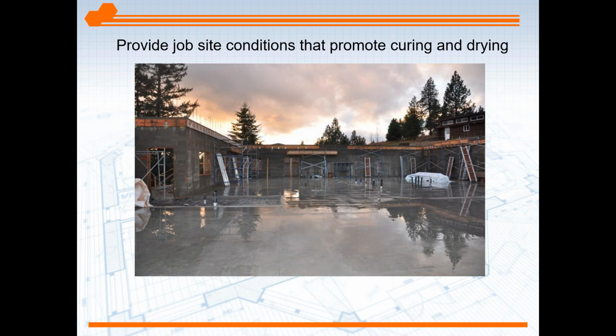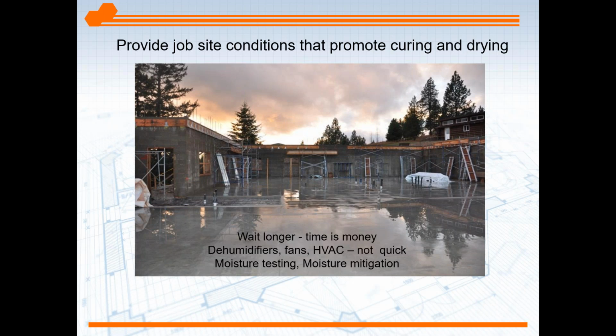If it rains, if a plumbing pipe bursts or leaks, if they wash the floor or flush it with water, if the fire sprinkler system bursts or leaks, we've got water added to that slab. And remember when I said it takes 30 days for every inch of concrete to dry? Well, the minute you introduce water again to that slab, a rainstorm, that clock starts ticking again. And as a contractor, you're walking on a job, you don't know what's been done to this concrete slab. The mix design, vapor barrier underneath it, what was it exposed to, other water? So again, you have to worry about possibly being proactive with moisture mitigation.